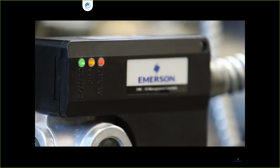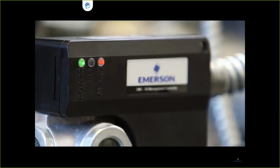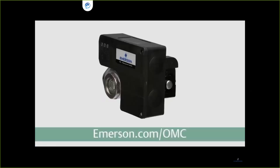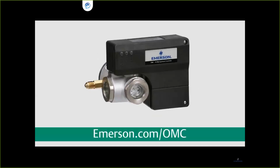The control will continue supplying oil, and the alarm will automatically reset when the proper oil level is reestablished. If 5 alarms occur within 30 minutes, the compressor lockout feature is enabled, which requires system diagnosis to prevent compressor failure. To learn more about the Emerson OMC Oil Management Control, visit emerson.com/OMC.